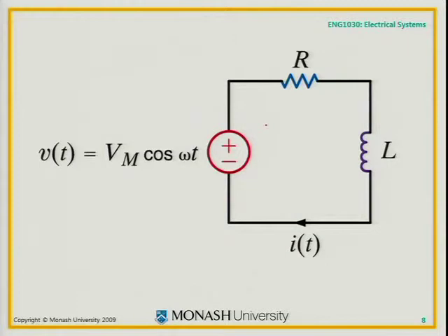So how would we analyse that? That's great. We've seen some MATLAB pictures, but where did I get the equation from? Well, we do the same analysis that we did last time. We do Kirchhoff's voltage law around that loop. It's just that instead of there being 6 volts there or some constant, there's Vm cos omega t, and that just changes the solution to the differential equation that we get. It's just another first-order differential equation. Now it's going to have a different solution because we have a different driving function. Okay? But from the circuit analysis perspective, it's Kirchhoff's voltage law around that loop.